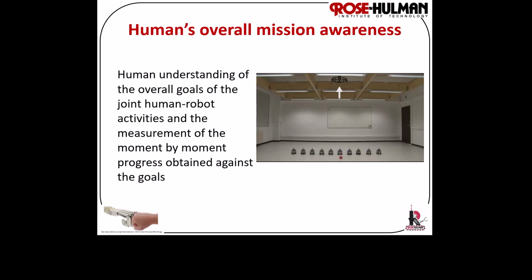Let's say a flying robot wants to communicate with a specific robot on the ground, this one, for instance. To start the selection process, the flying robot illuminates its red LEDs. To join the selection process, the robots on the ground light up in blue. In a series of elimination steps, each ground-based robot independently displays a sequence of randomly selected colours. At each step, the flying robot matches the colour of the target robot. Whenever a robot on the ground sees that its own colour doesn't match the flying robot's colour, it eliminates itself. The process continues until only the targeted robot is left.